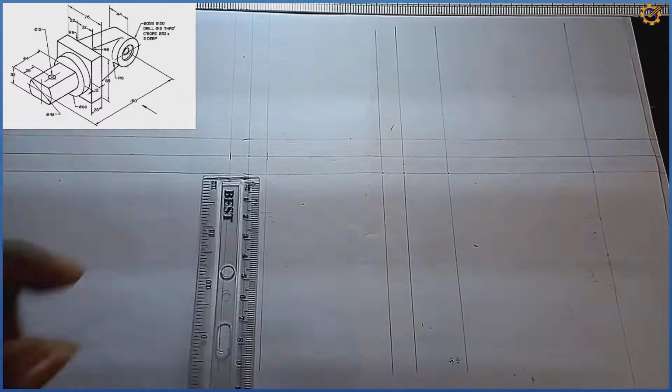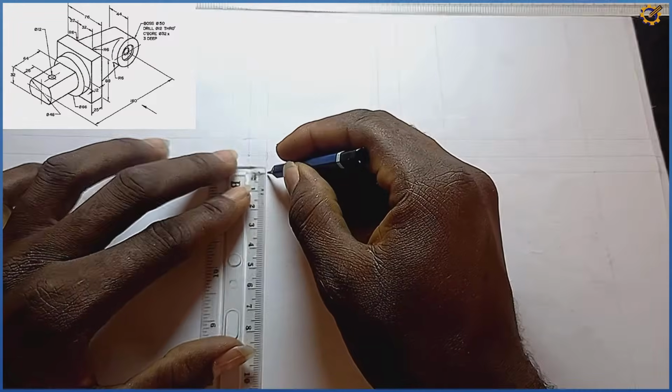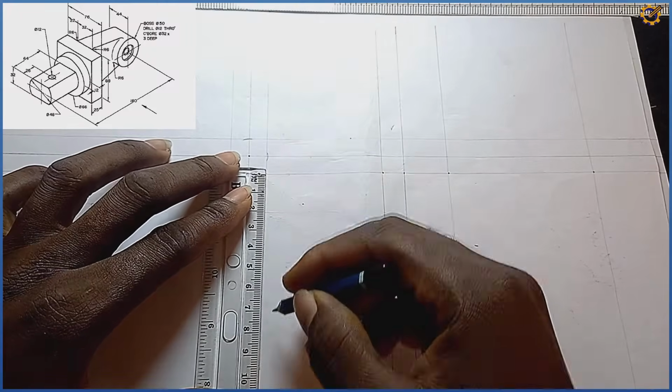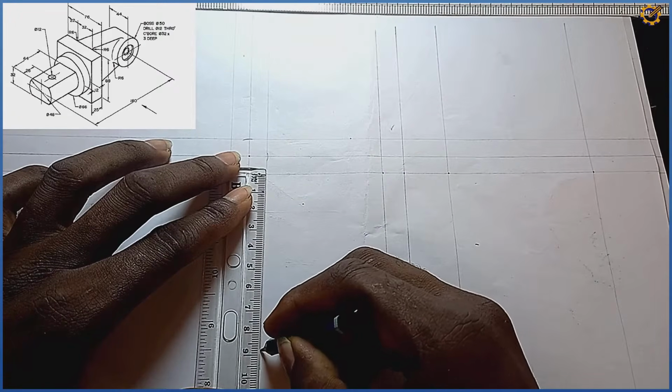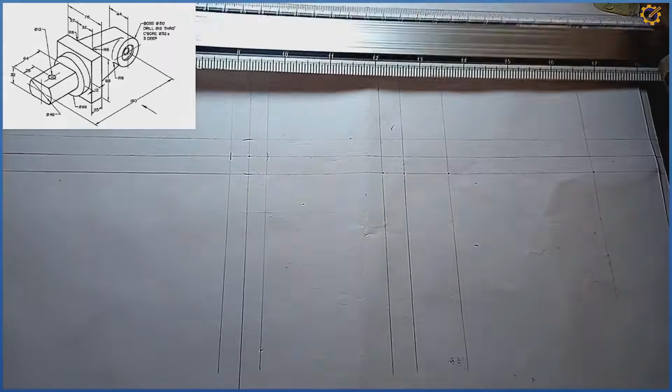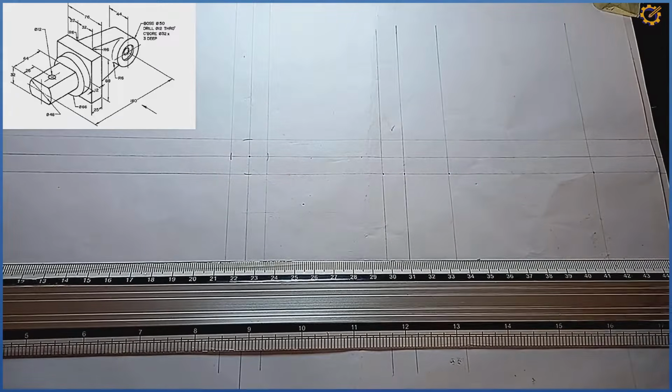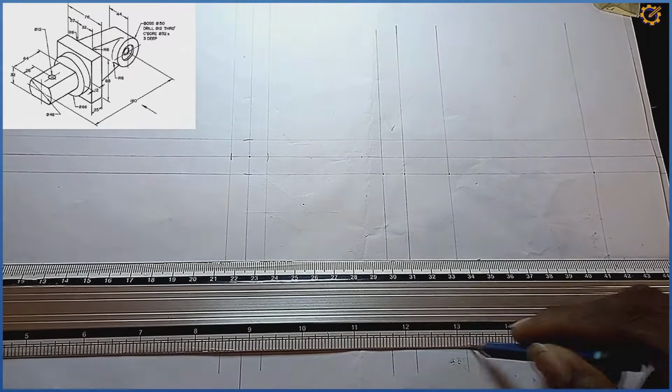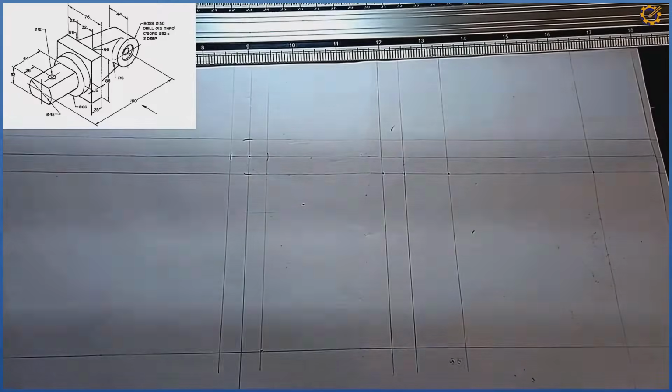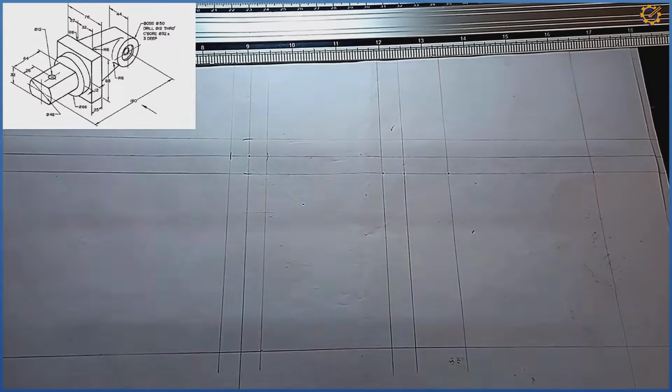After drawing all of those, our total height is going to be a mark of 88. Picking my ruler from this junction also, I measure a mark of 88 downwards. So this is the 88 right here. And I'm going to project it horizontally also, across like that, horizontally.